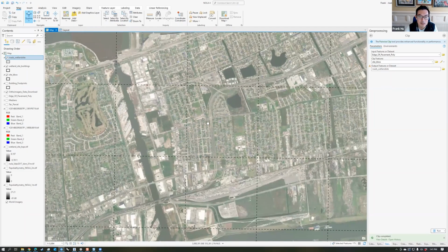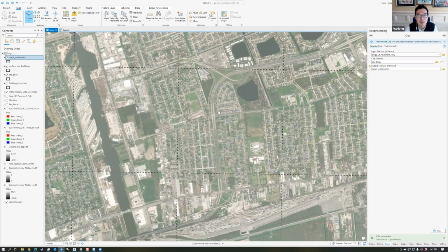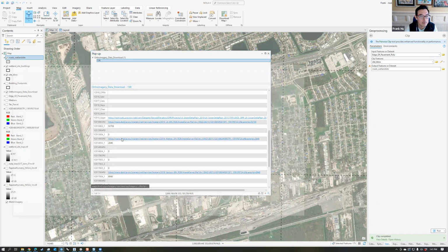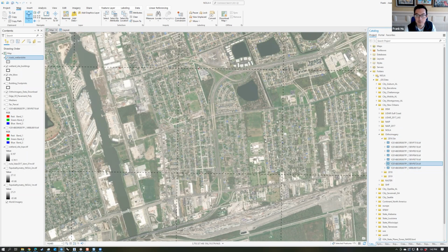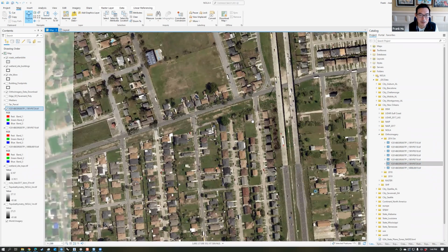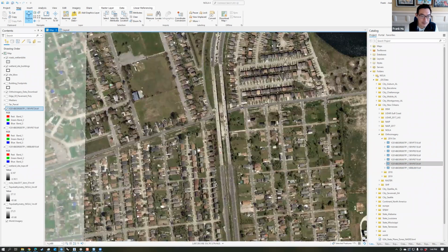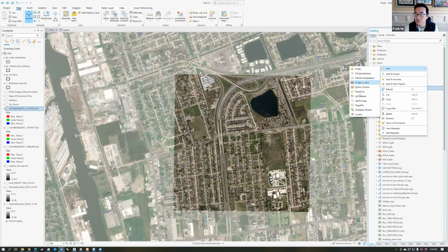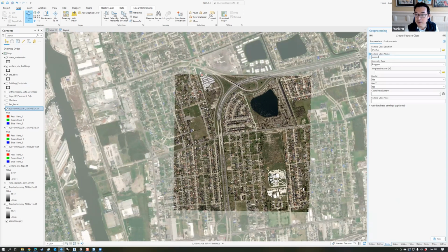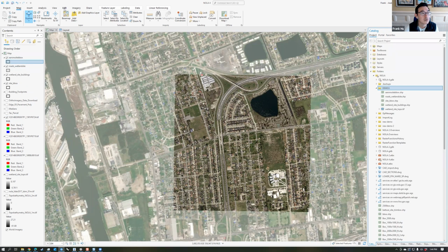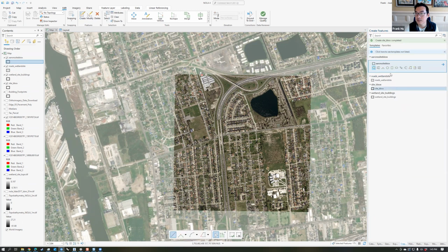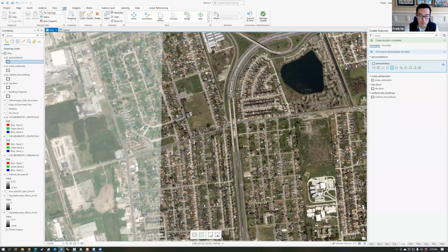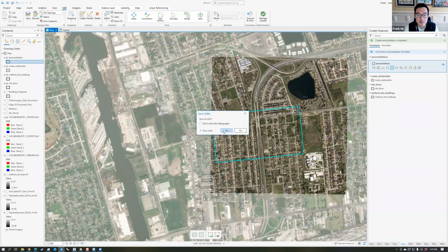And this is me just kind of winging it. So I'm going to click on that, download the aerial for that. Building pyramids. Okay, this is great. For Aaron's site, let's create a site bounding box. So right click, new shapefile, call this one Aaron's site bounding box. Coordinate system is going to be current map, run, go to edit, create, Aaron's site, rectangle. Then save that, save, clear.